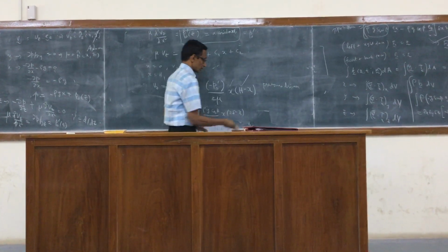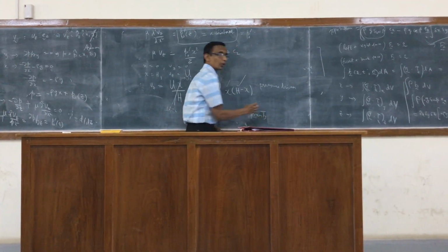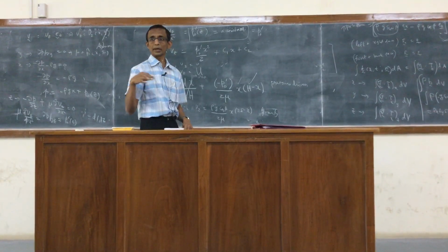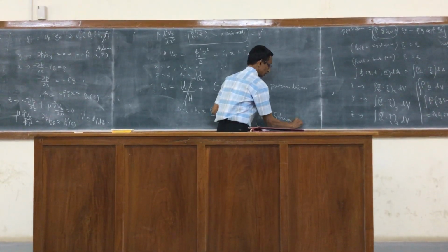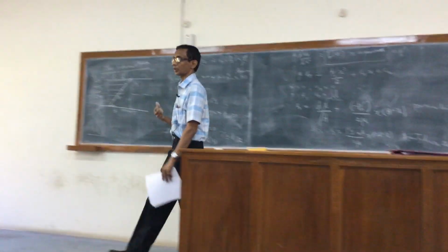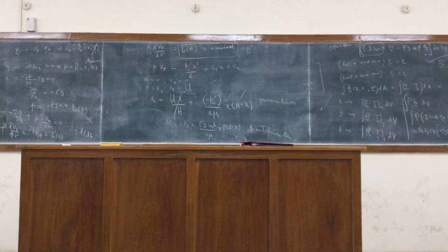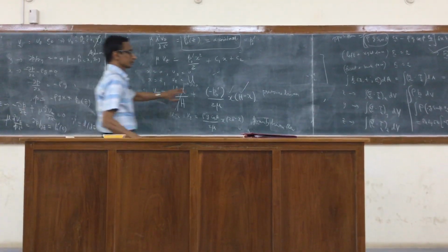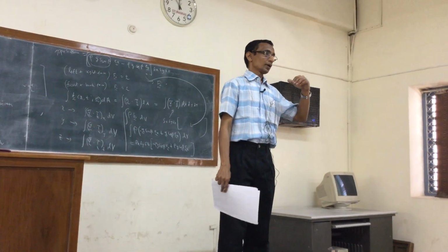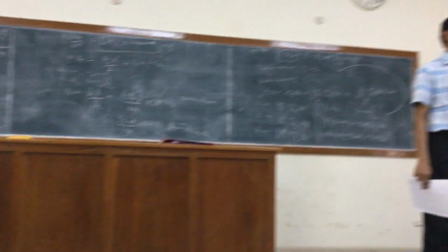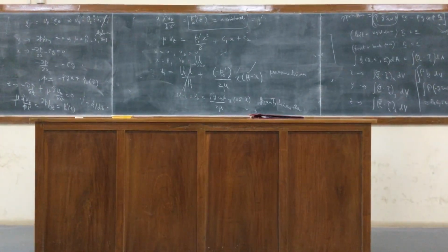So this is the complement of this. So here gravity is not driving the flow. It's actually normal to the flow. It's not contributing anything to the flow itself. In the other case, you have to recall that there was no variation of the pressure in the flow direction. Yet flow was possible because of the effect of gravity. That can be called as a gravity-driven flow. And this is a pressure-driven flow. So if there is no movement of the plate, then you can have flow only when there is a pressure drop in the flow direction. That's what it says. Right?